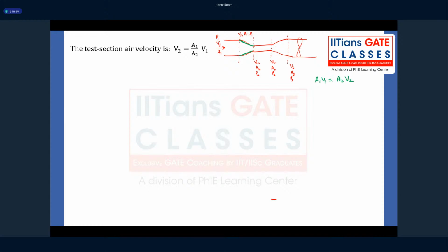So V2 = A1 V1 / A2. A1 and A2 are known to us from the construction of the tunnel. V1 is the inlet velocity, which is also known to us. So you get V2 from here. Once you get V2, similarly for the diffuser, the same mass conservation gives A2 V2 = A3 V3. From here, you will get V3, the velocity at the exit of the diffuser.